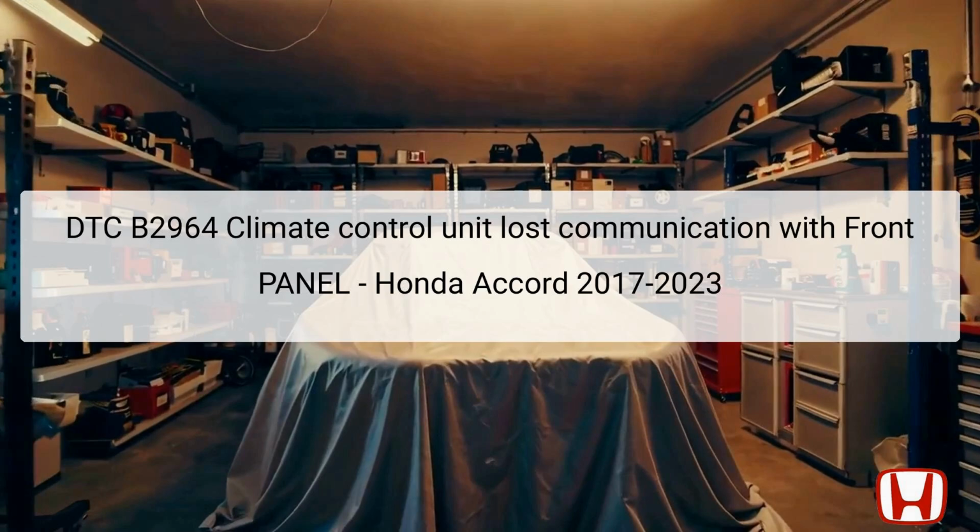The Diagnostic Trouble Code, DTC B2964, indicates that the climate control unit in the Honda Accord has lost communication with the front panel. This issue typically arises when there is a malfunction in the data transmission between the climate control unit and the associated front panel interface.